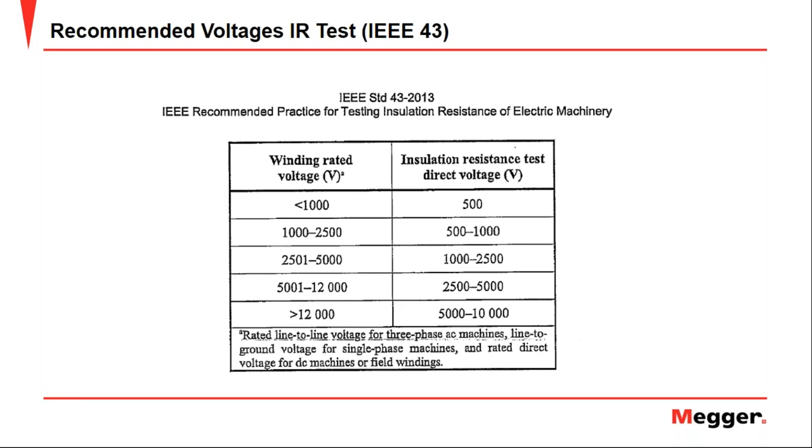Let's see. I think maybe for more than 10 minutes, the standard established that in 10 minutes, the insulation is going to be as polarized as it can be. So if you extend the time of the test, maybe you don't get anything more, because the value at that point, in 10 minutes, is going to be constant over time.